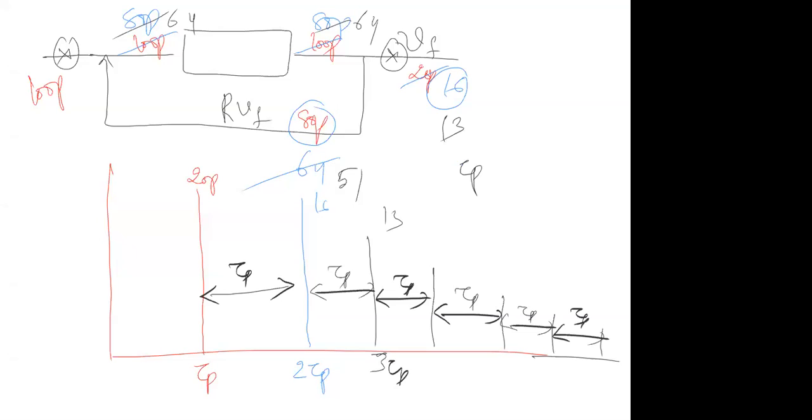So what is the residence time tau p here? How do you calculate tau p? Volume of the PFR divided by volumetric flow rate. What is the volumetric flow rate? V naught plus R into V naught, that is how your tau p is calculated. There are an infinite number of peaks, because 80 particles will go, then 20%, like this.